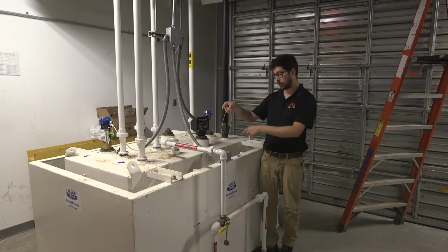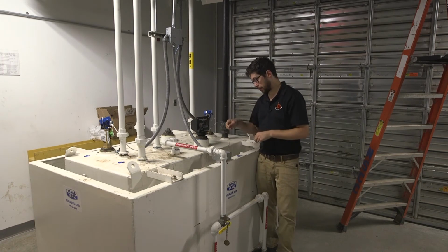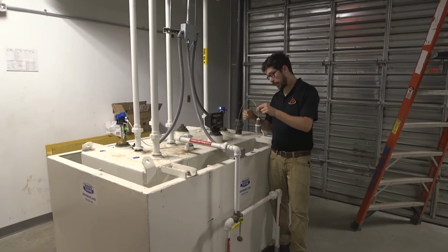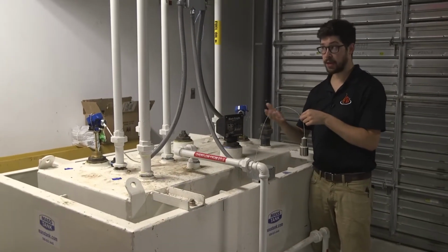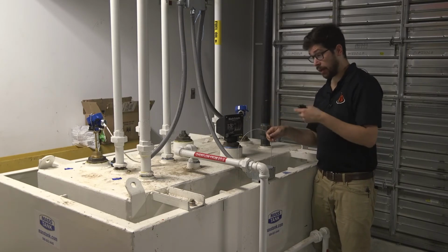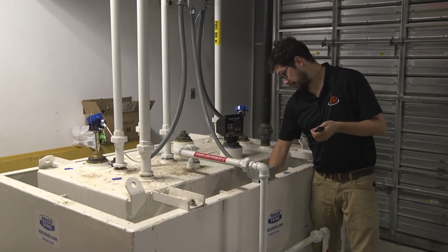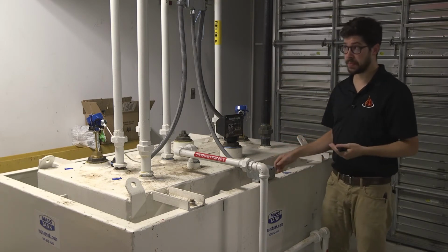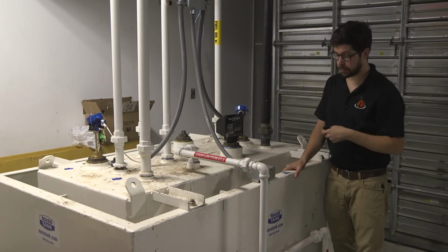Just like the other tank, we are monitoring it for leaks, which is this leak sensor here. It is just a float type, so a good way to test it is to just flip it upside down and wait a few seconds, and that will trigger the alarm. Simply, if this fills with any liquid, that little float in there will lift up and cause the alarm.